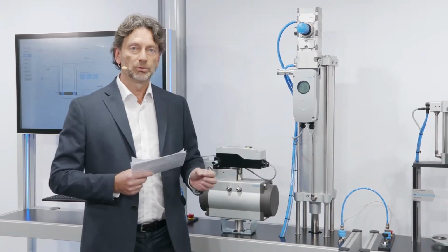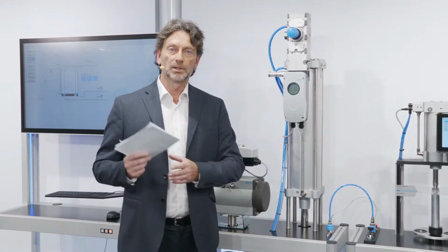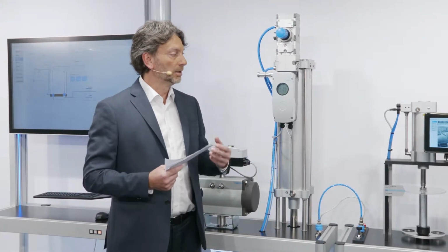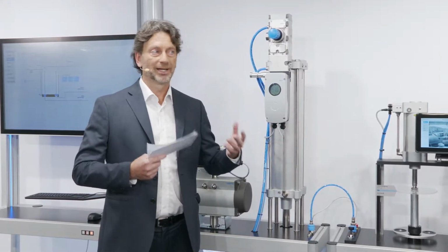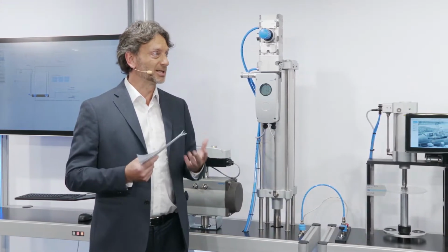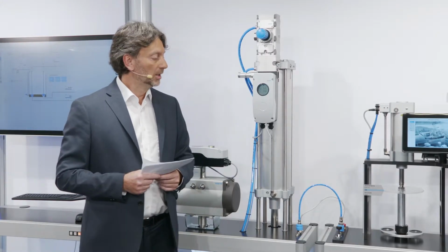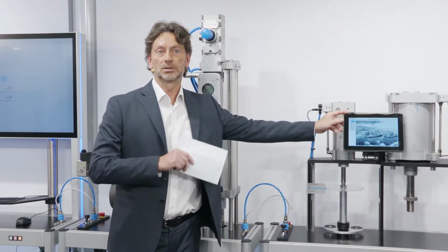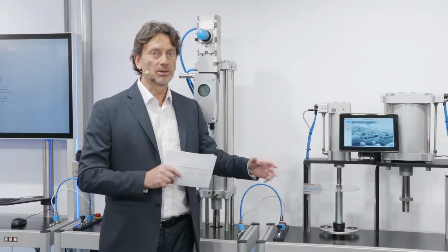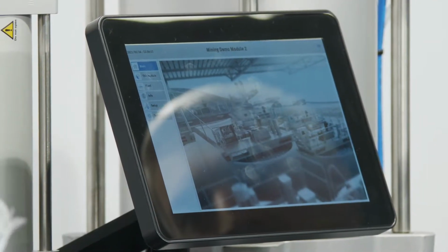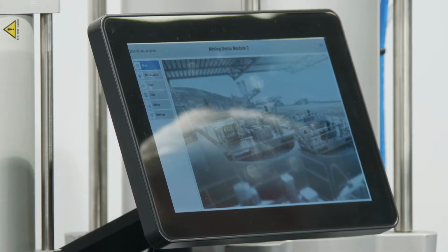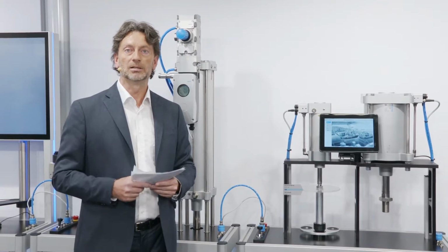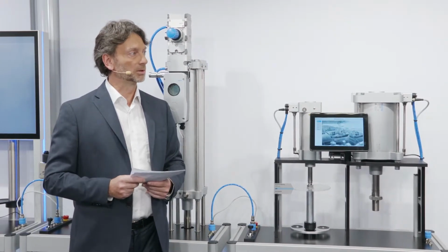And by doing that, we have the possibility to transfer the logic from the main controller into the local controller. So that being said, this package unit can run autonomously. It is a self-sustained unit. Of course, it is also a lot easier to implement a local control of the package unit, because having a controller on the package unit, on the remote I/O, you can easily get access to the visualization, to all the variables that are needed to build up a local control.